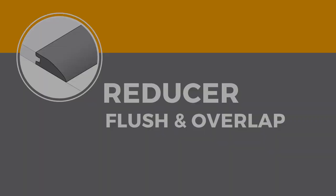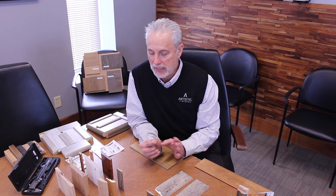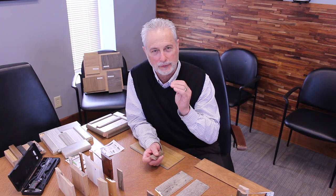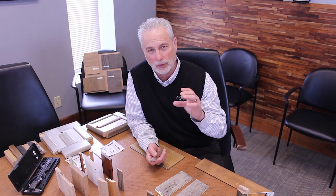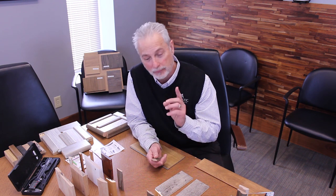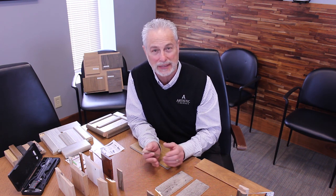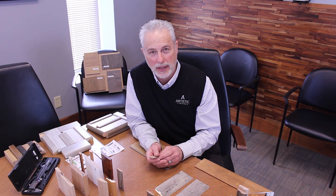Okay, next up would be reducer, the last of the big four. Reducers are very, very necessary when completing a job. You're going to have many situations where you have a difference in height from one surface. Say it's a tile floor and you've got a quick set underneath it, and with the tile being 3/8 and the quick set being close to that or maybe a little bit less, you create an unknown discrepancy or total height upon installation that may be unknown until the day that the job is completed. And so therefore the reducer becomes a very critical tool for that situation.